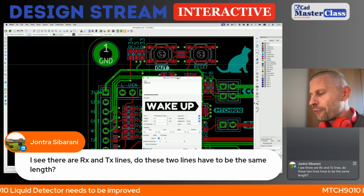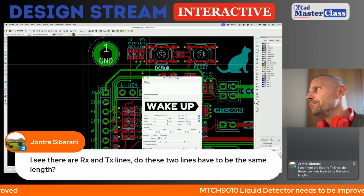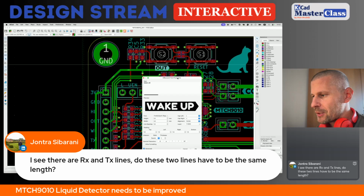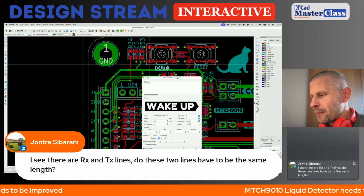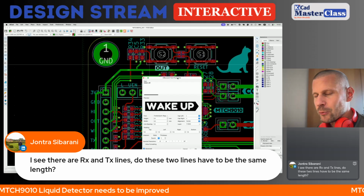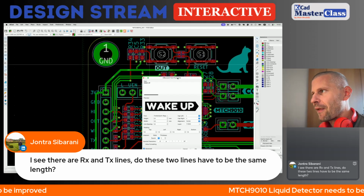Yeah, the rule of thumb is that you have to take care about the length tuning for the signals of the maximal frequency of 100 megahertz and up. And this a few kilohertz UART signal is not something like this.